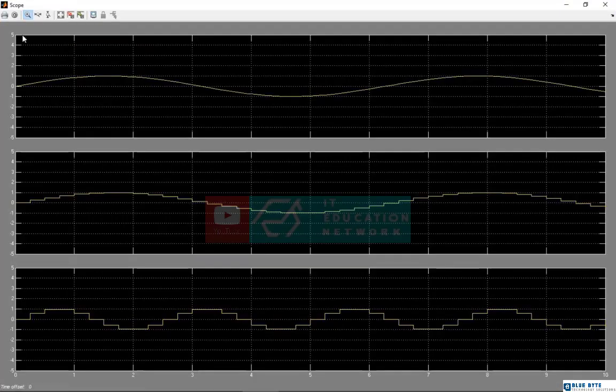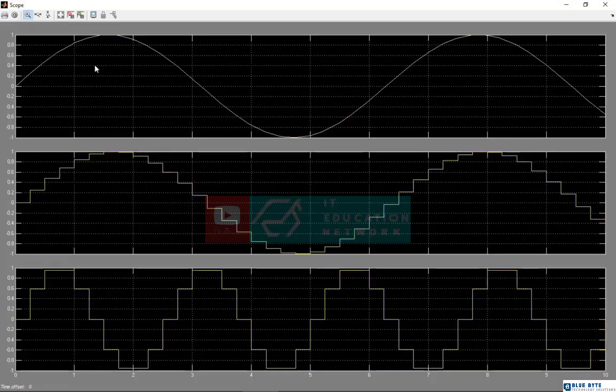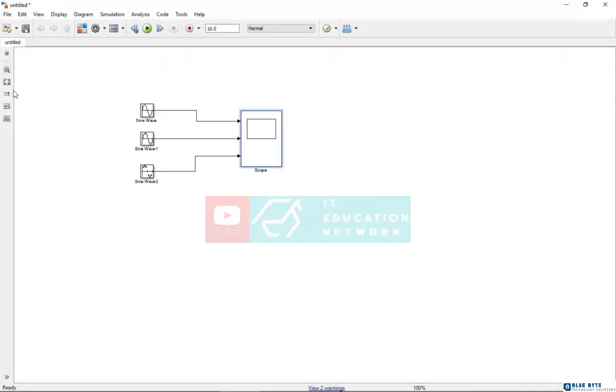As you can see, the first one is a complete sine function in the continuous form, and the third signal is simulated based on the sample time that we entered on this block, and it has a discrete form. The only continuous state was for the first signal, whose sample time value was 0. So you can create any sine signal, discrete or continuous, in your simulation.